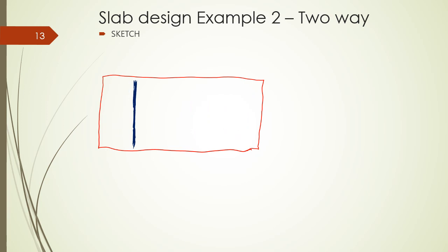Instead of doing that, we will take a leader and annotate this bar here, which I've said is T8 at 200 bottom 1, gives us 252 millimeters squared per meter.